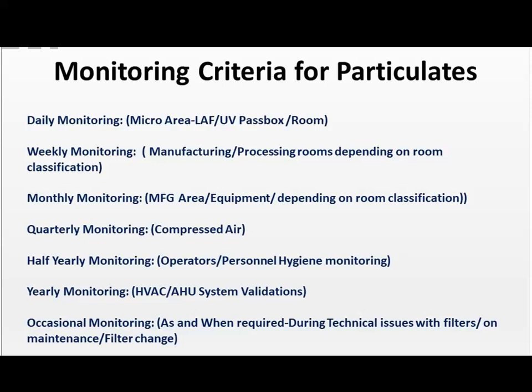We can do occasional monitoring when we have technical issues with filters or maintenance or filter changes. Then we want to be sure that if someone goes in and changes out a HEPA filter, or does some type of maintenance, that we do the proper monitoring then, because any time we are breaking something down or doing particular types of maintenance within our clean rooms, we're generating contamination. We're bringing bioburden in, and we're generating particulate contamination.